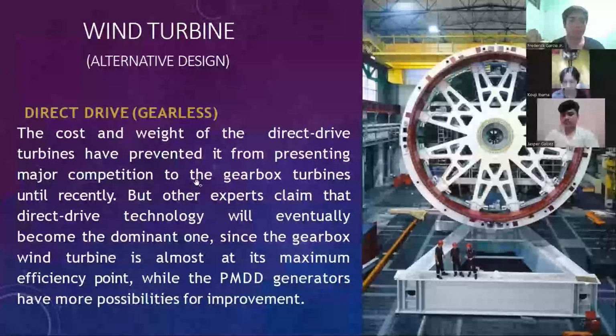Yes, so because the geared wind turbines have gears, these present mechanical losses in the energy generation. And so the efficiency at which these geared wind turbines generate electricity has stagnated or plateaued. So the future possibly would be direct drive gearless, depending on how the generator is designed.